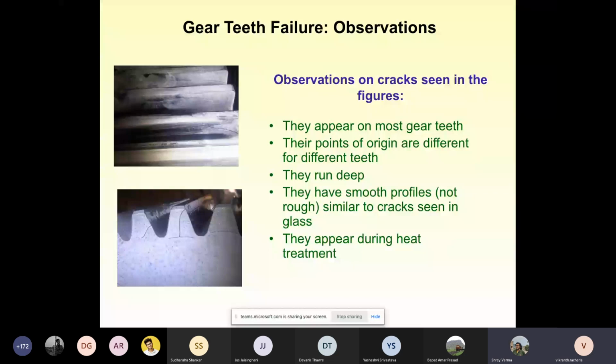But sir, the cooling rate is different for different parts of the gear as well. There could be some difference, but what kind of a microstructure might have resulted in the gear for it to become too brittle? Bainite. Martensite. There could have been a very big martensitic transformation within the gear. Bainite is also quite tough actually, but martensite is very brittle.